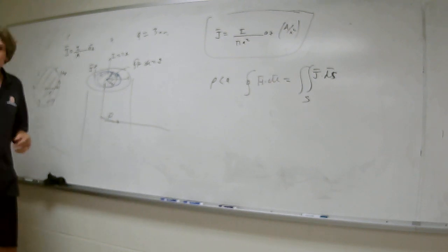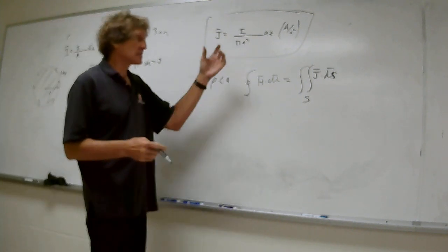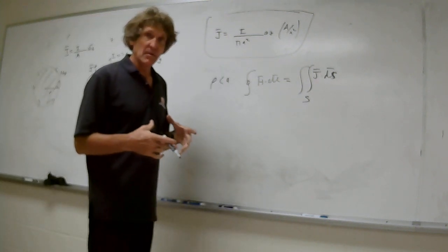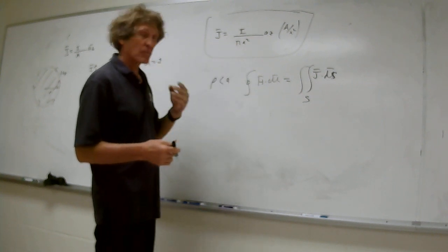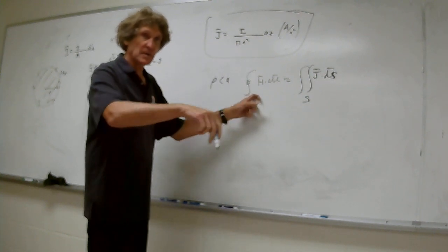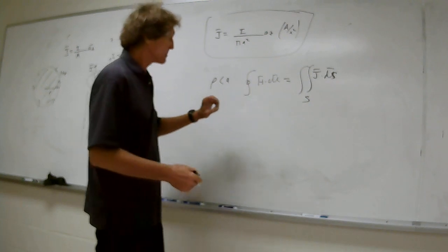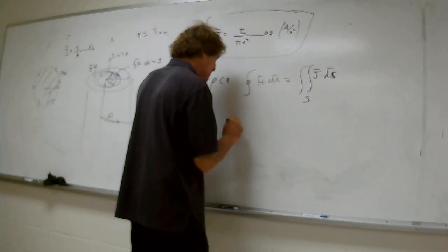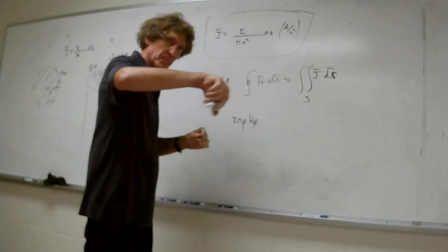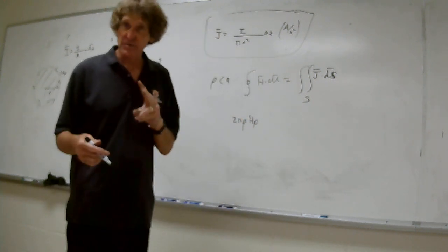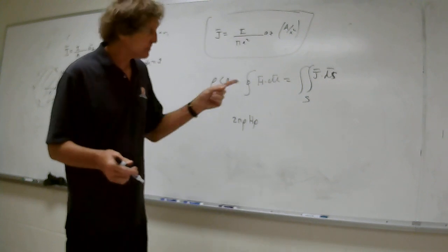Because the current density is a constant, you can just take the current density times the area. If it wasn't constant, if it was a function of radial distance, then you'd have to perform the integral. For anything that's circularly or cylindrically symmetric, this will always be 2 pi rho times H phi. It's just the circumference times H. Do y'all follow me?